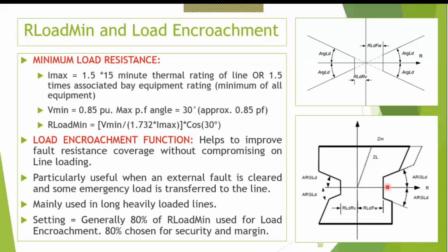I can carry emergency load on the line. I can use it for heavily loaded lines. The load encroachment function should be used for long and heavily loaded lines. Otherwise, the zone 3 is quite high, the infeed factor is quite high, so you have to set the resistive reach a little bit more to catch the high resistance points.